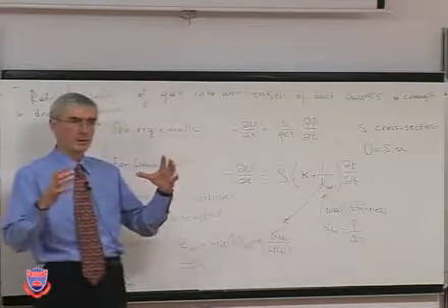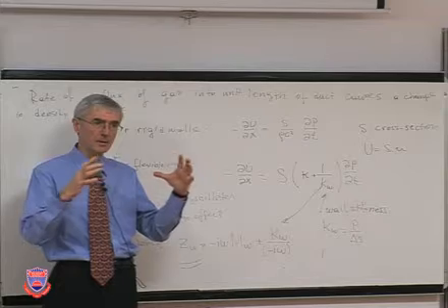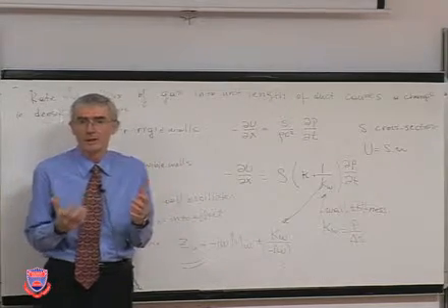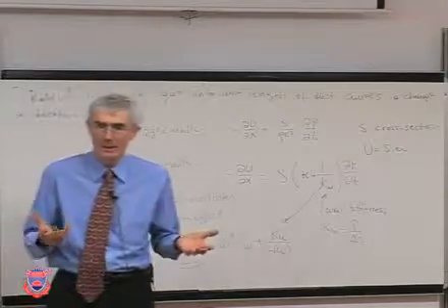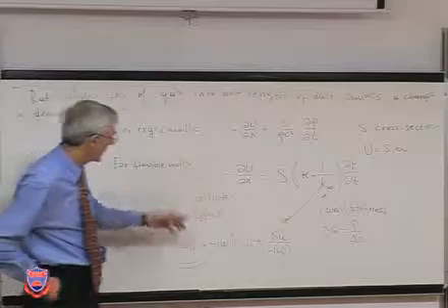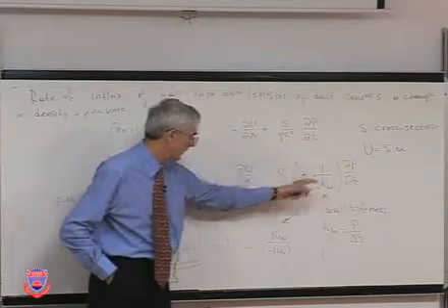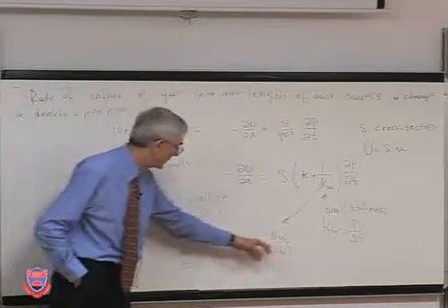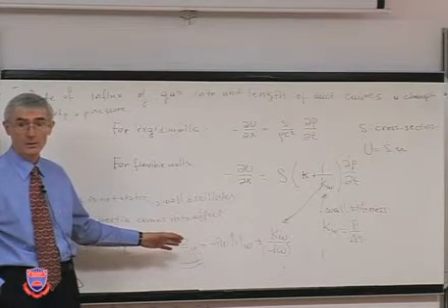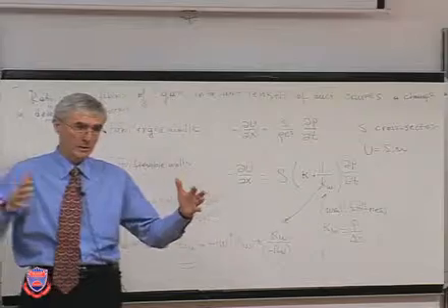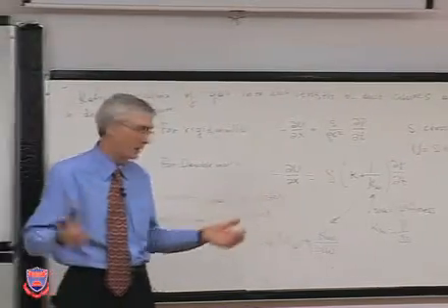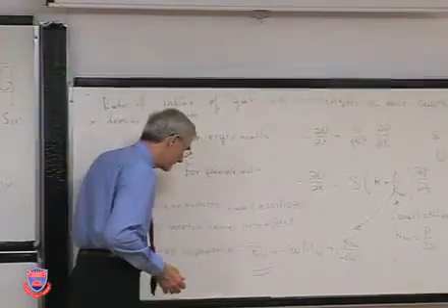But now we're saying that it isn't just the compressibility effect, you have a wall that's moving. It's not a membrane. If it were a membrane, its inertia may not be important. But now it has its own inertia. And then instead of Kw, we now utilize the full impedance of the walls. Walls have stiffness. If you push it, it comes back. Okay, it also has a certain amount of mass.